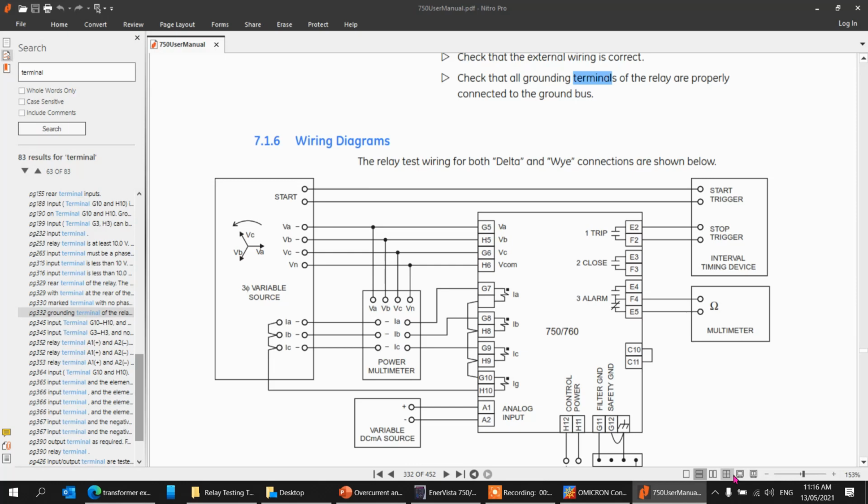Without disconnection, if you don't want to disconnect because the client doesn't want to isolate the control. So we leave that F2 as well. You just squeeze in your lead on F2. So that's wet contact, because there's still voltage there. But that works if the control system is solidly grounded or earthed, the negative of the DC is earthed.